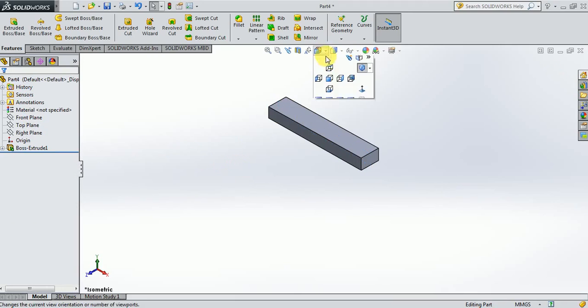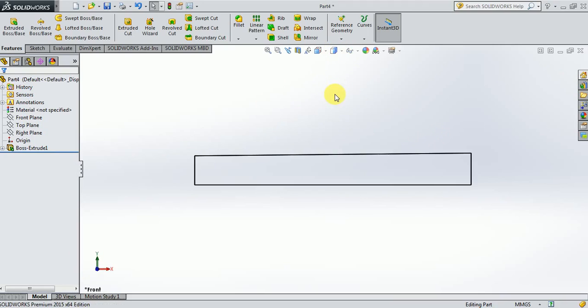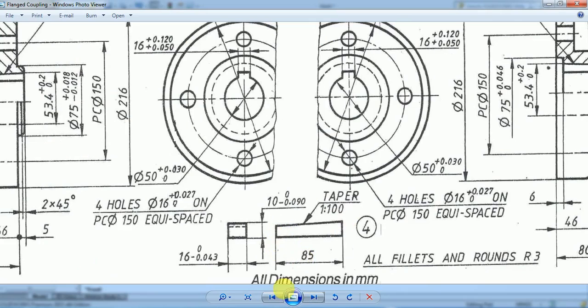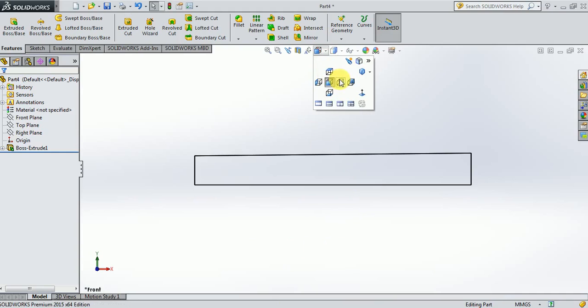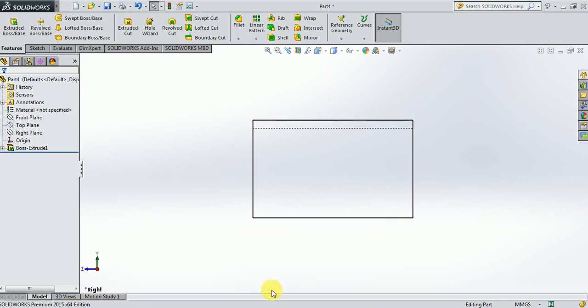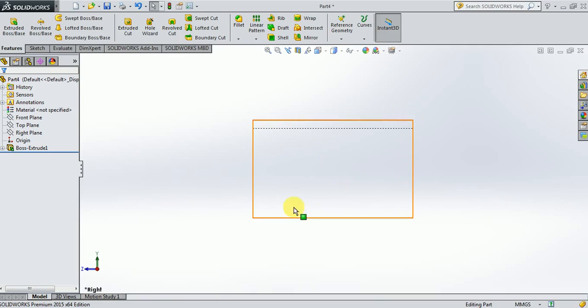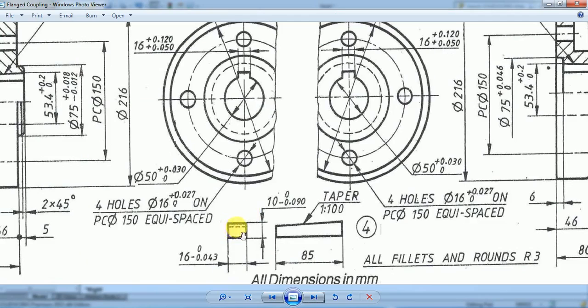Now if you try to keep it in front view, this is how it looks. Let me change it to the solid wireframe mode, with the hidden edges. So this is how it looks. This exactly matches with this front view here. And if I try to see the right view of this key, it is going to look like this. So this is exactly the same as this. The right view is looking like a rectangle with a hidden edge here. That hidden edge is also shown here.